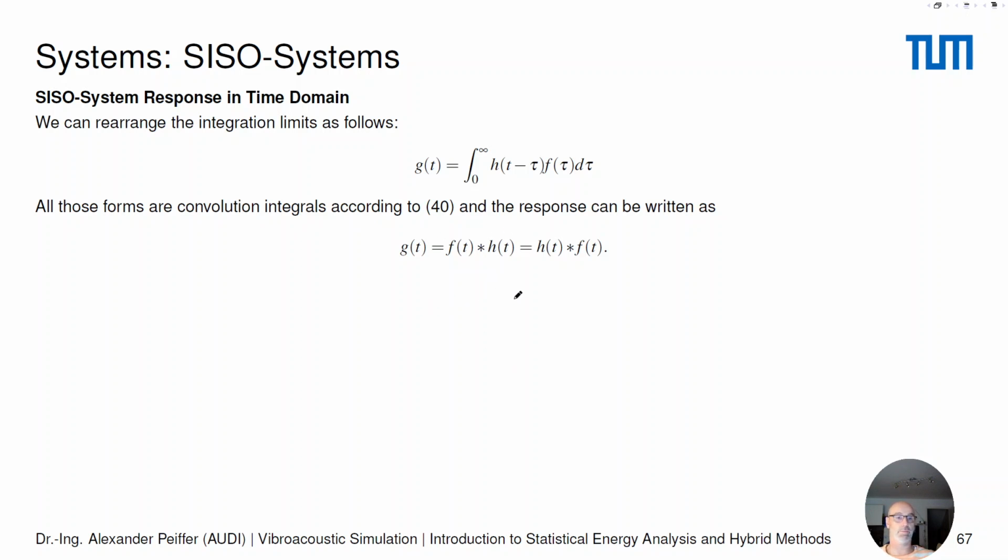So the operator of convolution is denoted by this famous star symbol. Also very important, please don't mix the convolution with the correlation, because they look similar. If you keep in mind, convolution is always with a minus, the correlation comes with a plus, which has a different meaning. So there's no comparison of signal, it is just heading in the other direction.